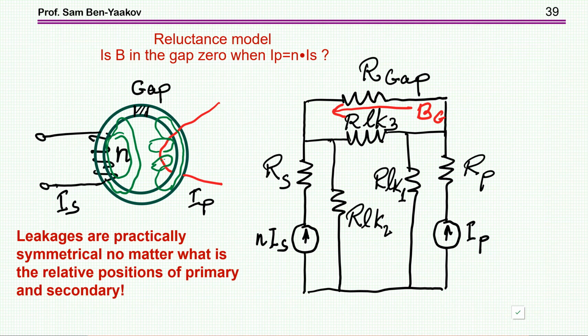In the videos that I have posted in YouTube, I've said many times that leakage is not part of a winding. It is in between winding. That is the flux that is lost in between the winding. And the example I'm giving is like a road between two cities. The road does not belong to one city or to another. It's something in between.